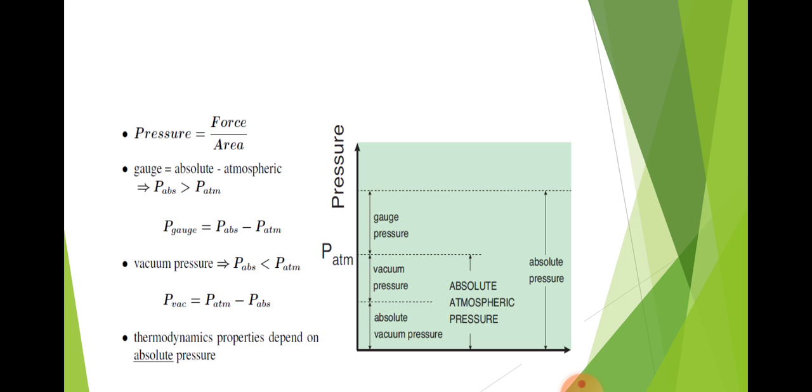At sea level, 760 mm of mercury column at 0 degree centigrade is taken as a standard barometric pressure. This is also known as the atmospheric pressure. To express this physical atmosphere in kilogram per square centimeter, we must first determine the weight of the column of mercury with a cross section of 1 square centimeter and a height of 760 mm.